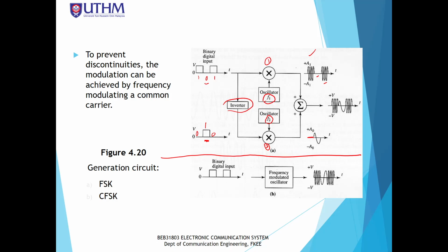That's why you see a single sine wave here compared to the 3 or 4 sine waves produced by the first balance modulator. This is because frequency F2 is smaller than frequency F1. And input logic 0 produces 0 output.